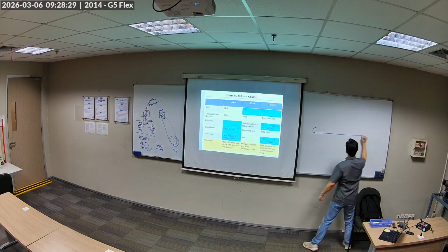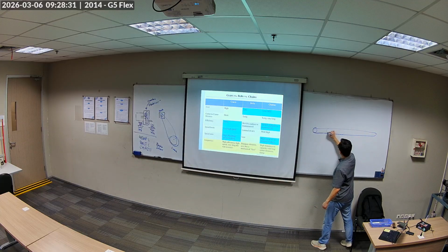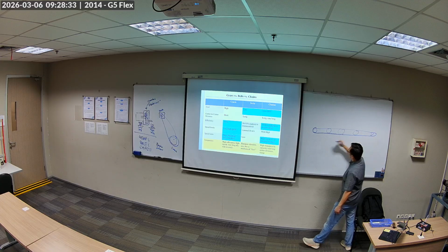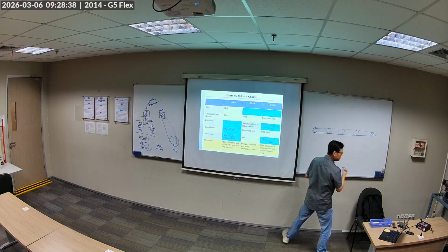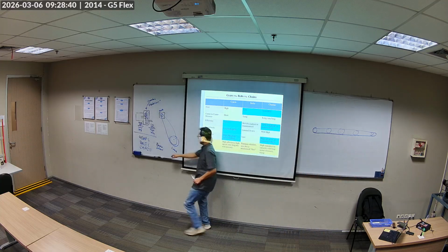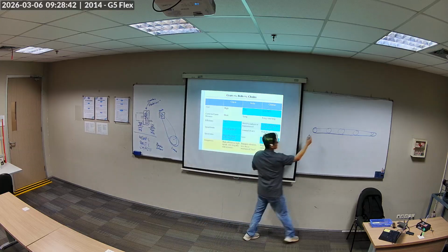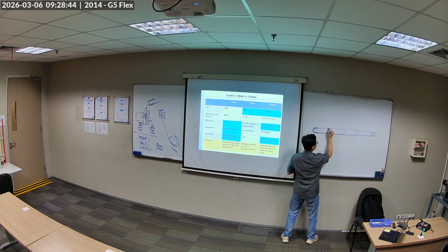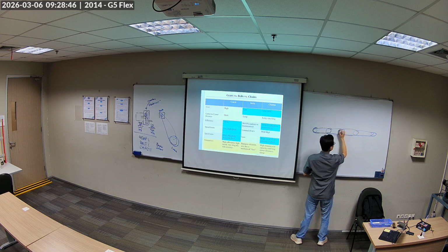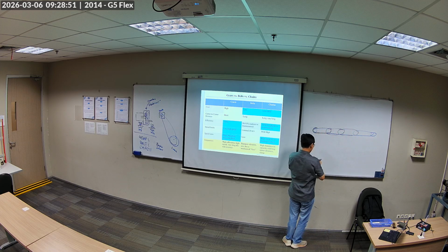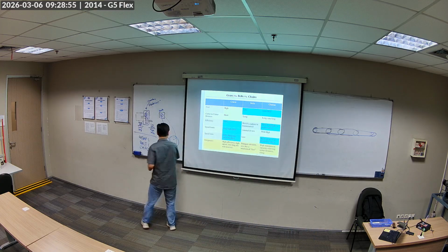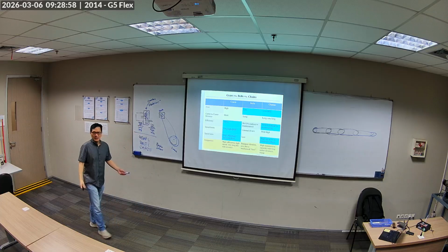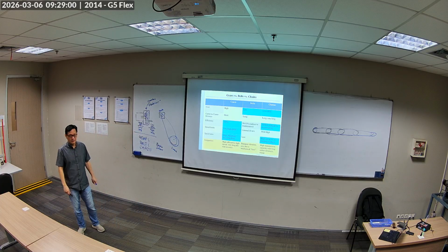So say you got a really long conveyor, and this can be attached by chain. So you can have chain like this, and then like this, and then like this, or you can have one long chain. So with chain, you can get very long center distance. That's because it doesn't stretch. Belts stretch.